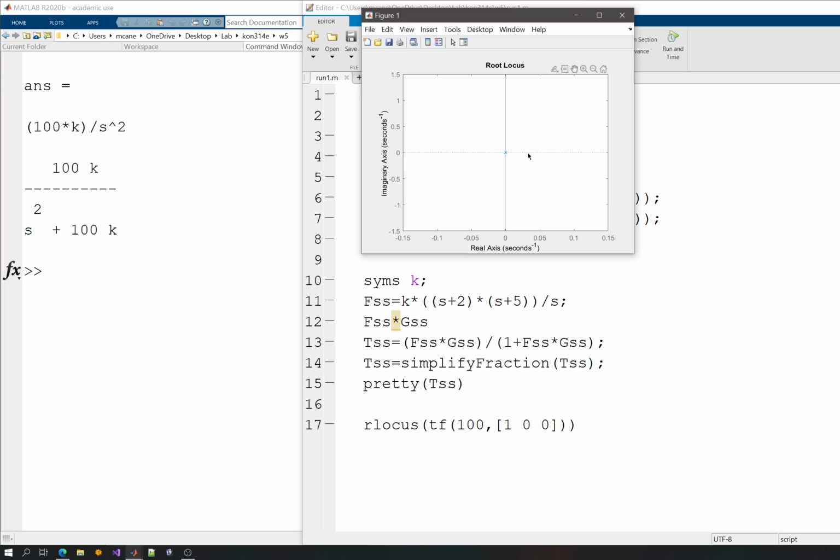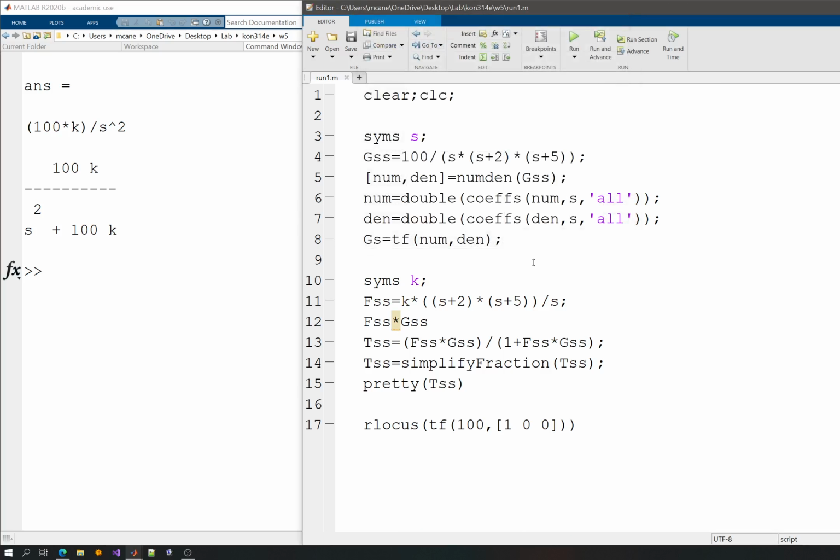But since I don't aim to design an oscillator, and I'm trying to design a closed loop system with certain transient dynamics and a tracking in the steady state, this is not ideal, and I'm not able to cancel out both zeros in order to get a stable closed loop system transfer function. Basically, in some cases this might be possible, but in our case it's not possible.